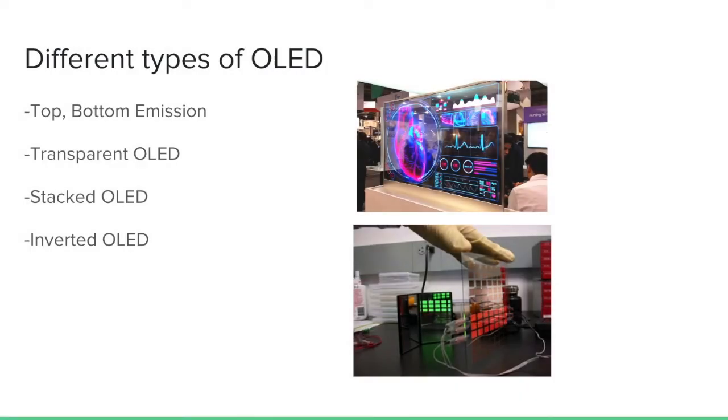Hi, I'm Liam, and I'll be going into part 2 of our report. There are different types of OLED. The first one we're going to go into is bottom emission. Bottom emission OLED devices are devices where the light emitted passes through the transparent bottom electrode as well as the substrate that the panel was created on. AMOLED are typically created with a non-transparent bottom substrate, leading to light being blocked if the device is bottom emission. So this is generally used for the other type.